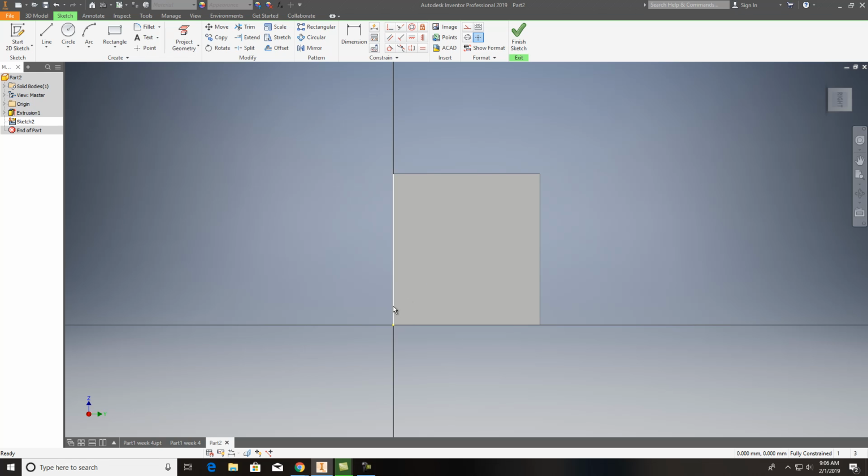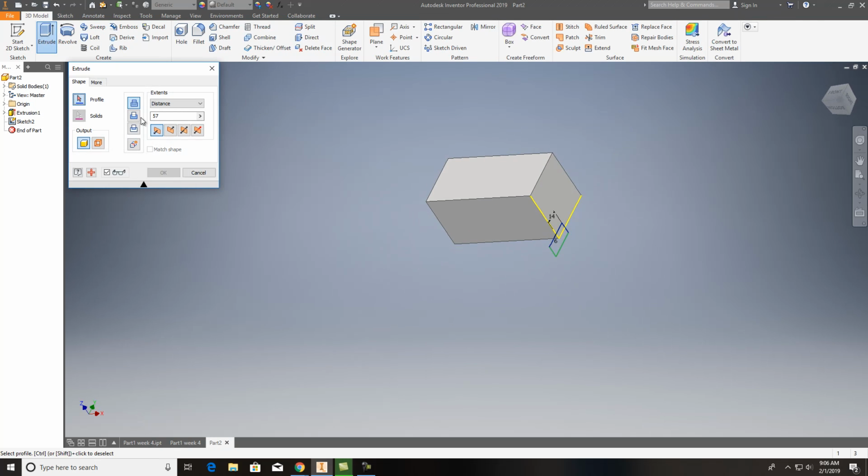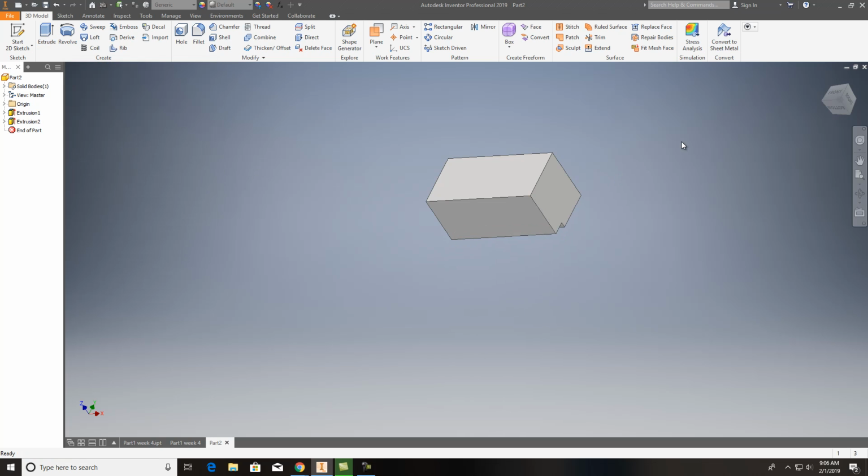It looks like it's got a little block cut out here, so I'll go ahead and knock that out. And we'll do a dimension here to there, which looks like 14. From there to there, it looks like it is 6. To finish the sketch up, I want to extrude that by using a cut, and I want to go all the way through it. Cut that out. So we got that part of it done already.